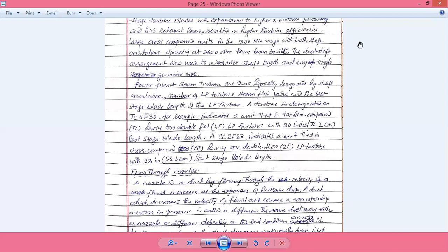In the straight flow turbine for a large unit without reheat, the steam may expand through the initial section and then exhaust to another turbine itself. So there are other turbines defined as high pressure turbine, intermediate pressure turbine, and low pressure turbine. This means the steam, after expanding through the high pressure turbine, may be reheated again to regain temperature and go to the intermediate pressure turbine. Then it can be either reheated or not reheated but sent directly to the low pressure turbine.